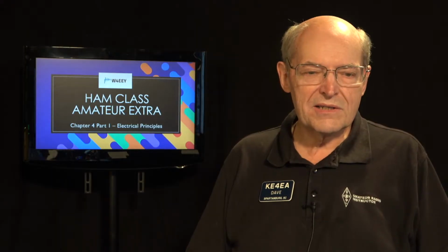So I'd take the TV apart, and the power transformer would be plugged into 120 normally, and then have all different voltage outputs. And I'd use an ohm meter to figure out which windings were which. And I was really surprised sometimes when I would disconnect my ohm meter. It was an analog ohmmeter, probably had a 9-volt source inside, and when I disconnected it, I got a very nice zap, and that's because of this field collapsing.